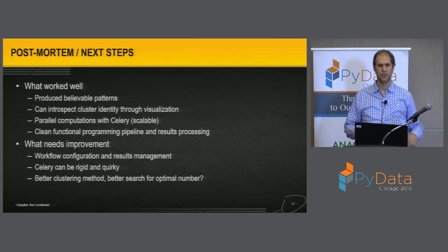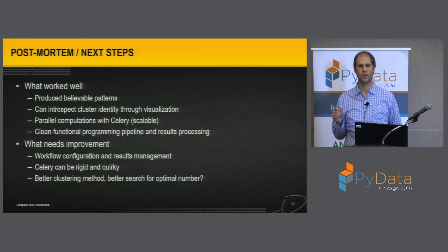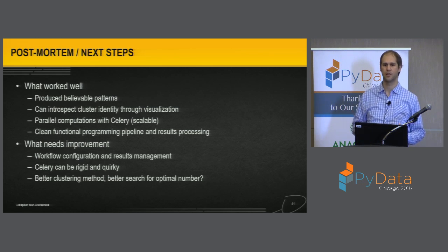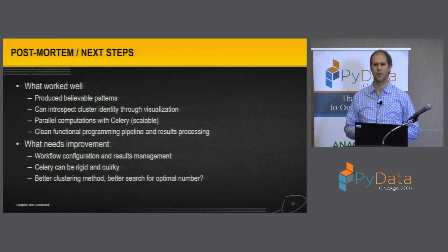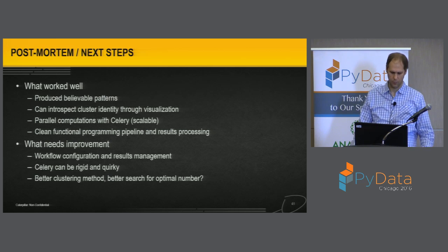What needs improvement? Over time, we had to run this many times. We would find errors in the feature code. For example, when throttle's at 0, call that a percent of time that you're at 0. Turns out when the guy is at 0 in the cab, the signal might be at 0.01. So we have to go run a whole job and find out that the feature needs a little margin, change the margin, rerun it, and then it improves. So doing that over and over again, we found that we needed a better workflow management and a way to compare results one versus the next iteration.